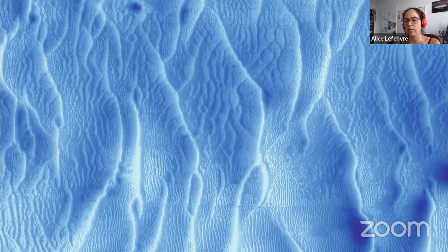Sometimes we don't have a lot of influence from the waves because they are blocked before really entering the estuary, but we get storm surges. That's when we get flooding in Bremen. If there is a high tide and a storm surge, the dikes get flooded here. That is something we would like to look at as well, because it's going to change the hydrodynamics definitely a lot. Gerald was also talking a lot about the effect of wind, because it's the wind which is pushing the water, which is making those storm surges. So he wanted to look at that.